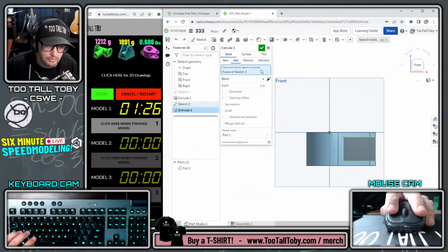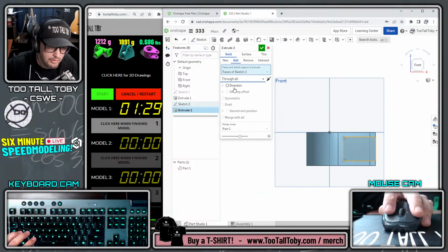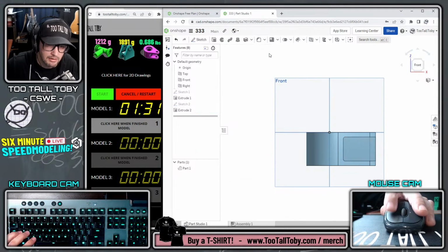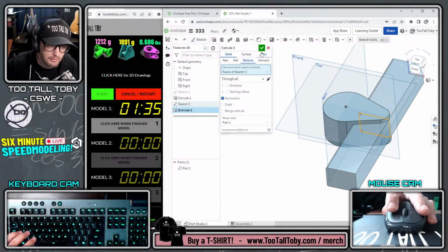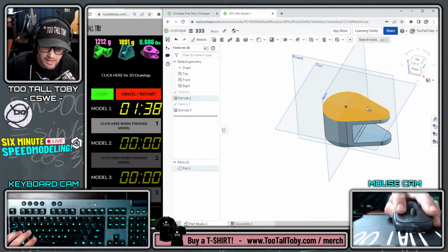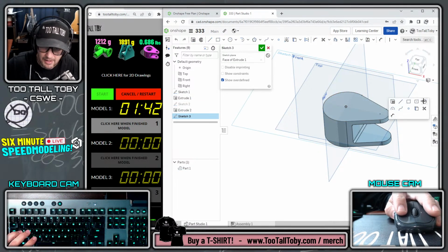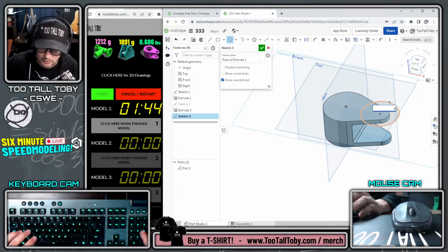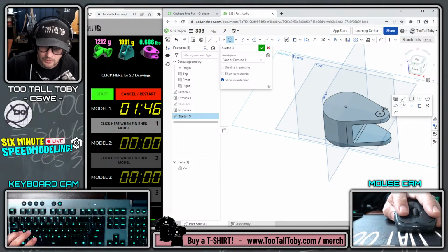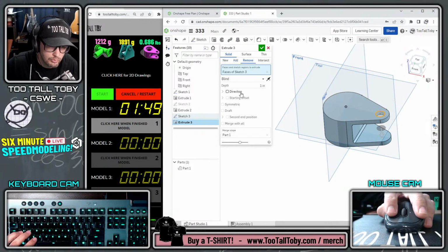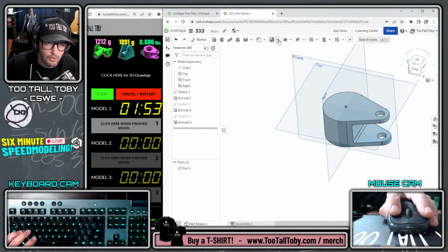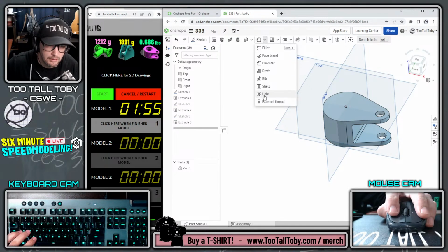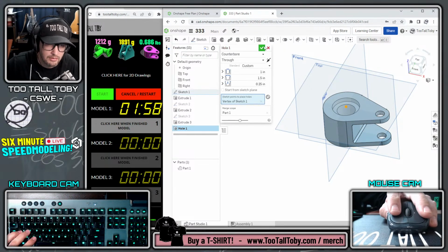And we're going to extrude cut that through all in both directions. So we'll use symmetric here. Hit the green check mark. Whoops, that should have been a remove. Okay, easy enough to change that. Now I'm going to go to this face here and create my 0.5 circle, and we're going to go to extrude through all. And then we'll finish up here with our hole, which is going to go right here.